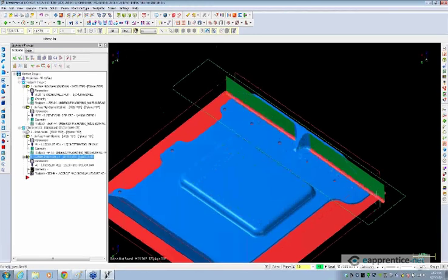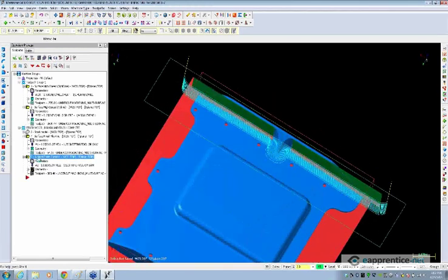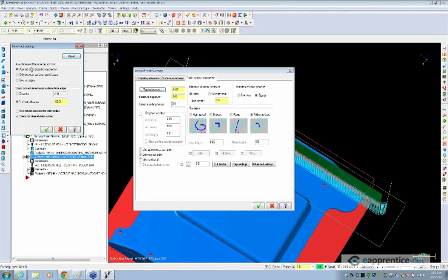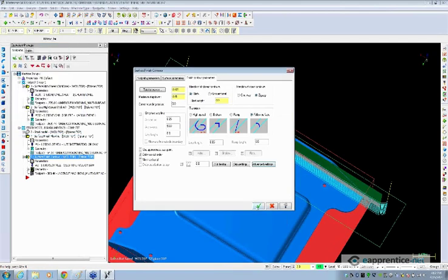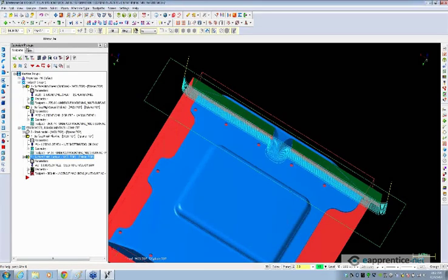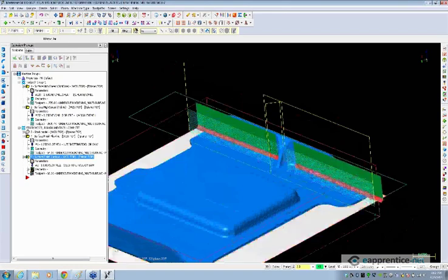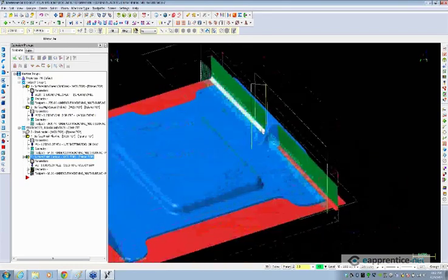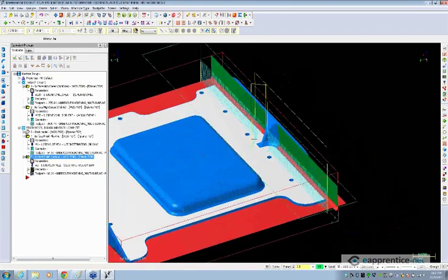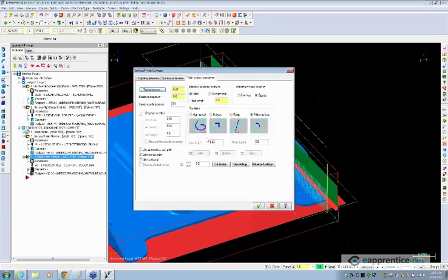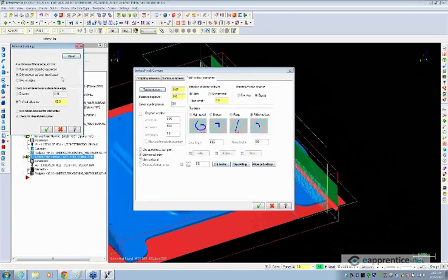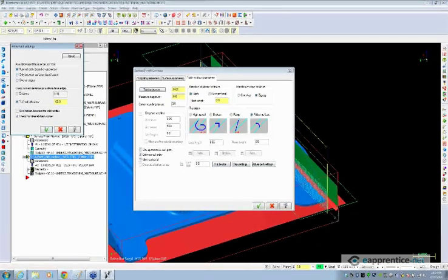Okay, so the other thing that we can do, we may be able to stop that with the rolling motion. So right now it says, at surface or solid face, edge, roll the tool. If we set that to only between surfaces, that's the other way that we can end up eliminating that motion. But you'll notice that it doesn't allow the rolling around here. So it's kind of a catch-22. It's a trade-off. Let's go ahead and set that back to automatically.